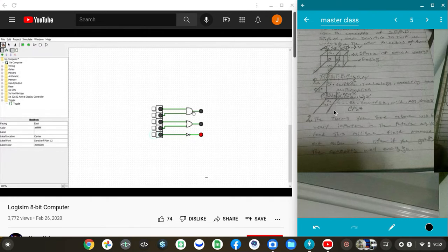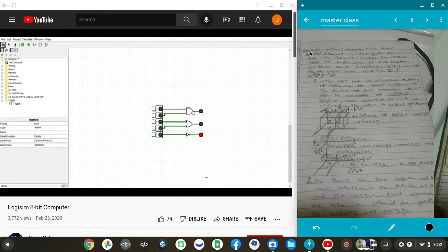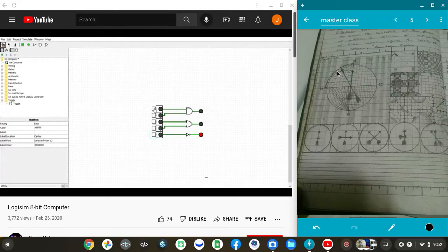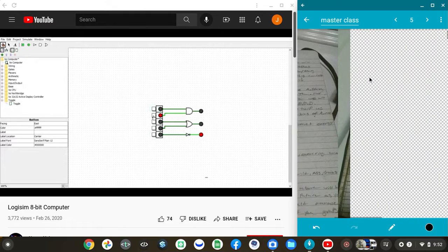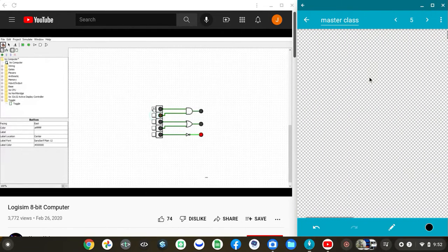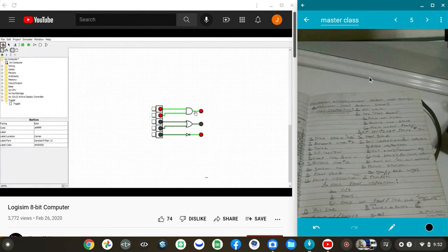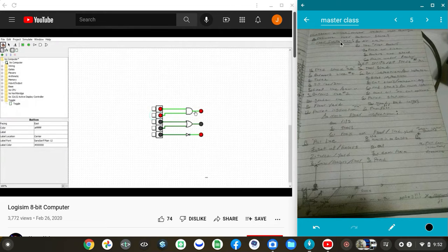So this is an AND gate, and it's called that because, let's say, these two things are inputs A and B, and this is the output. The output is on only if A and B are on. So if I turn A on, nothing happens. If I turn just B on, nothing happens. But if I turn A and B on, then the output is on. Another way to refer to this, instead of saying on or off, is true or false, where false is off and true is on.